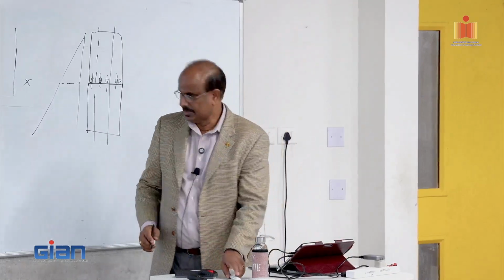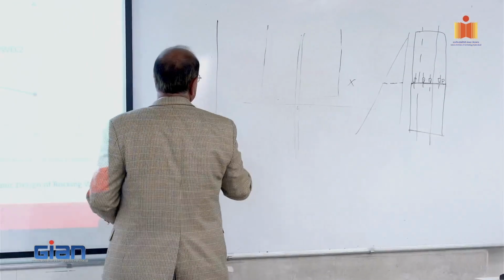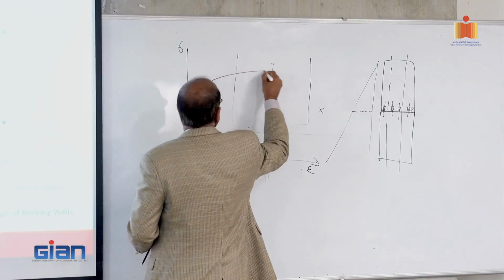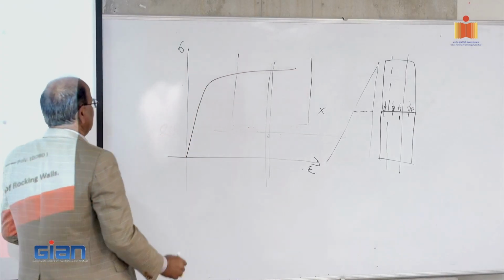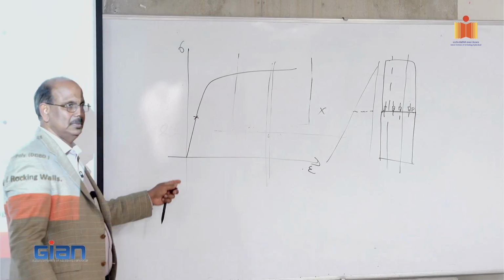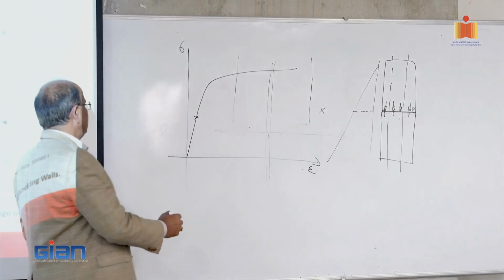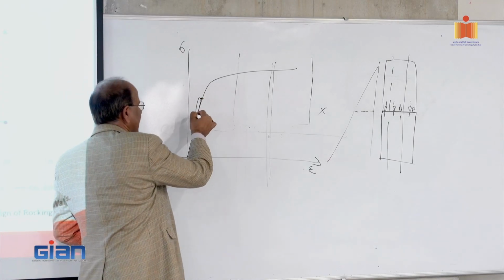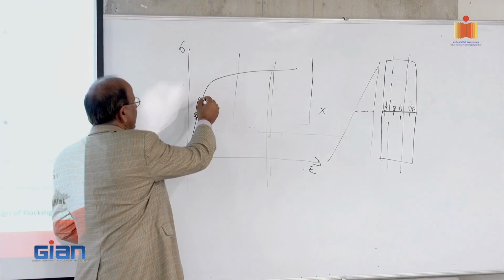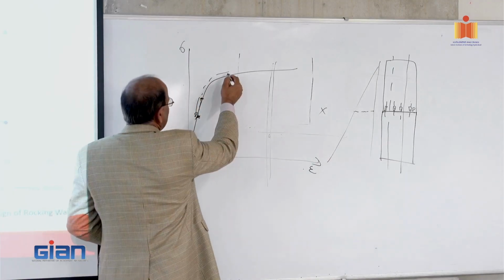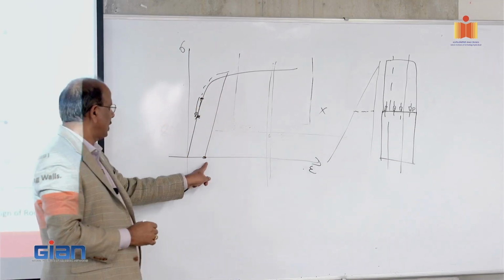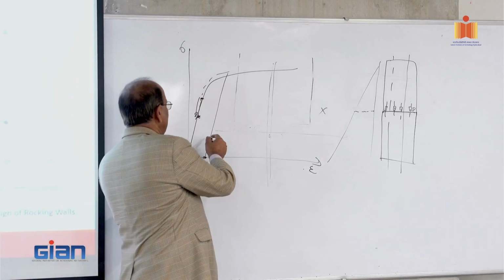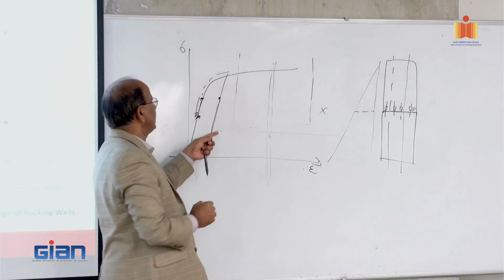So typically, as I said last time, if this is strain versus stress for the pre-stressing, let's say this is your curve. You design them to be here with the initial stress. During the earthquakes, they go up to somewhere here, and then they come back to this. That's the ideal situation. Occasionally, you may go somewhere here, and then you come down here. If you come down here, obviously you lost the post-tensioning, and you have a permanent strain. So if you stretch it again, it's going to go and stay here.